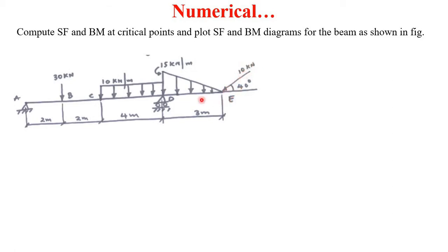Now what we have to do is calculate the shear force and bending moments at all critical points, that is at point A, at point B, C, D, as well as at point E, and we have to draw the shear force and bending moment diagrams here. So draw this figure, then we will solve this numerical step by step.